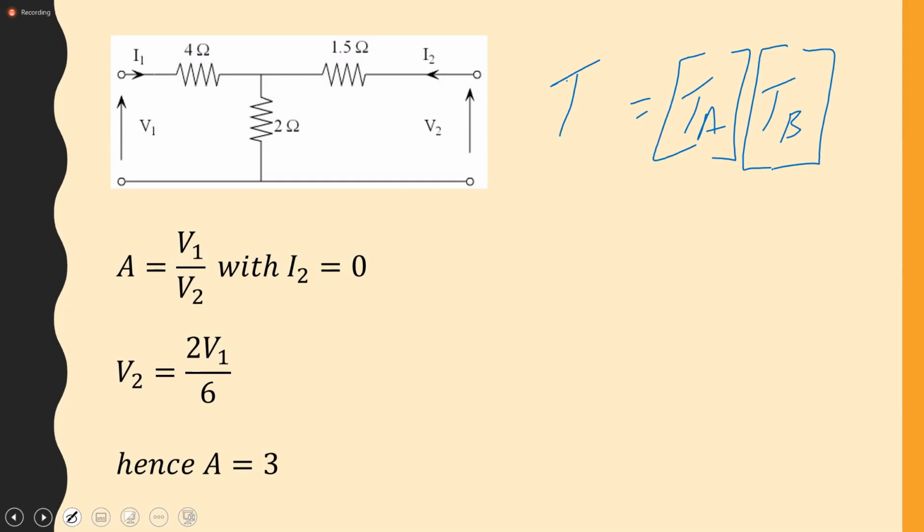So that's our objective. So I'm just going to go directly to finding the transmission parameters. If you feel more comfortable, what we're looking at here is a simple T network. If at this stage you're more comfortable finding the admittance first, then fine, go ahead and do that. If you're more comfortable with finding the impedance, do that, and then convert them to transmission.